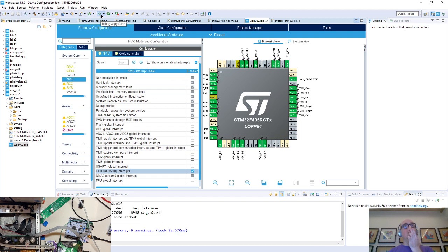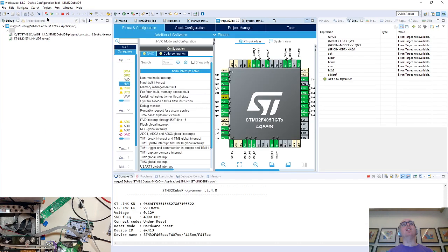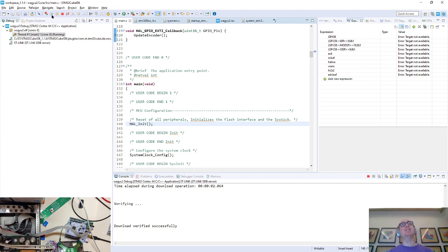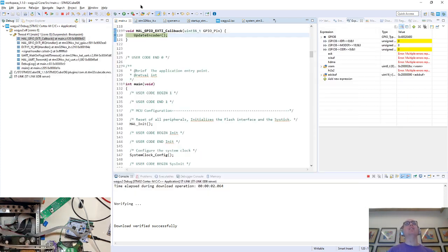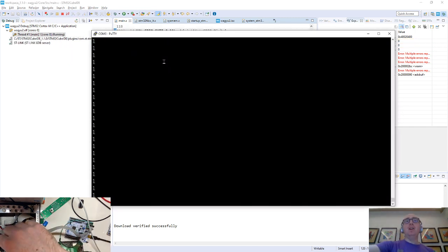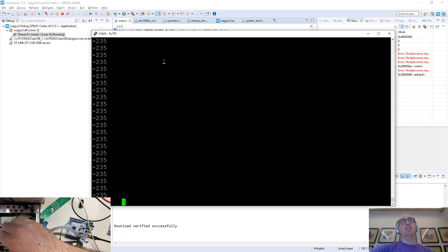Debug. Okay, take your bets, people. Second time lucky. Take me to hell in it. Oh, draw your screen twice. You can do it. Hit play. When this stuff runs this slowly, you can kind of see all the hilarious. Oh, I got a breakpoint. Indeed, I twiddled the knob and I got a breakpoint. 1. Woo! So I'm turning it right and the number goes up. I'm turning it left and the number goes down. And because we had a breakpoint, we're actually offset by 1. Normally these are like round multiples of 4, because basically it generates 4 edges per click. You can even hear it clicking probably. This ASMR.